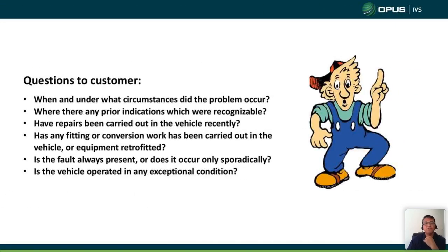So, questions to the customer: when and under what circumstances did the problem occur? Is it hot? Is it cold? Is it in a driving condition? Is it stationary? Is it while driving at slow speed, under load? Something like that. More information from the customer will make it easier for us to diagnose the complaint.